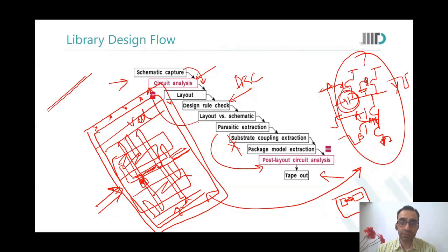Yes. Okay. Now I understand, sir. I was only concerned about the output, but not about the exact effect of this capacitance. Look at it like this. Without these capacitances, the delay could be 500 picoseconds, and that could be well within your specification. As soon as these capacitances come, your delay increases to 550 picoseconds, which could be out of your specification. So what do you do?